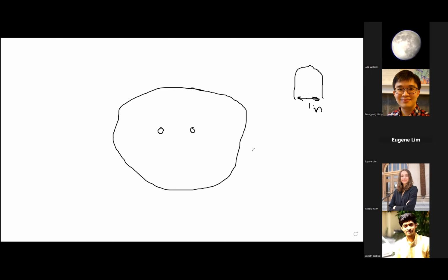Now, with parallel dimensioning, what we might do is take the center of this bulkhead and measure everything relative to that center. However, in this case, what really matters to this bulkhead isn't necessarily the parallel sense of keeping the holes each individually controlled.